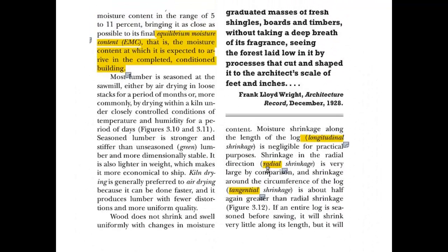The other thing that we do with wood is make sure that we get the moisture content down by putting it into dry kilns. You can let it season. When we talk about lumber being seasoned, that means it has its moisture extracted to the point where it's no longer what we would consider green. Kiln drying is where we're kind of forcing it. We're putting it in a heated shed where the moisture is extracted and taken away.